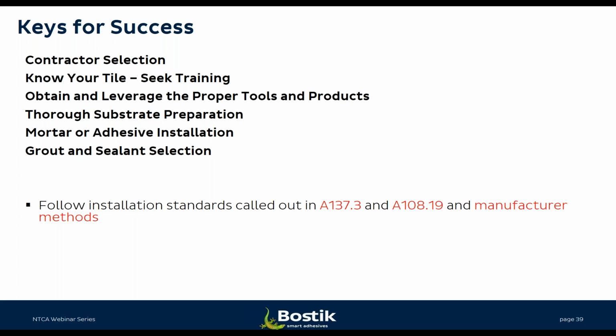So that goes not just from the actual types of trowels that are required and the suction cup racks, but also the substrate preparation materials, whether it's primers, patches, levelers, the lippage control tuning systems. If it's the mortars and or adhesives, those are critically important as well, and they've really advanced significantly to fit more of the needs of large format gauged porcelain tile panels.